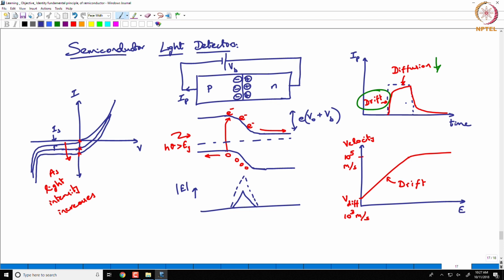So those will contribute to the initial photocurrent, and then you have the slower charges coming out of this photodiode, right. The ones going through diffusion would have a slower time constant. They will come later, essentially, right. And what we have fixed with the PIN structure is that now you can get a response something like this.